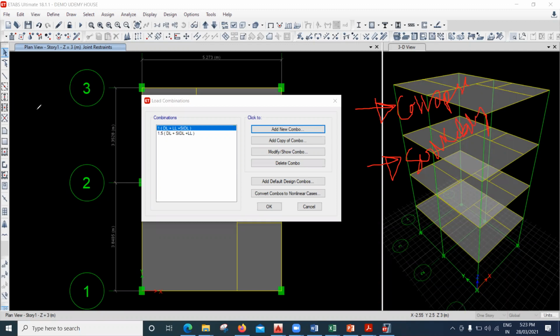Let us say I have a building here, let us say I have a slab here. Okay, and on this slab let us say 50 kg of load is coming. When I try to design this slab, I don't design my slab only for 50 kg, keeping the future point of view. In future this slab may be subjected to some 60 or 65 kg of load, right? I cannot predict that exactly. So as a structural engineer, I'll always go with something called a factor of safety.